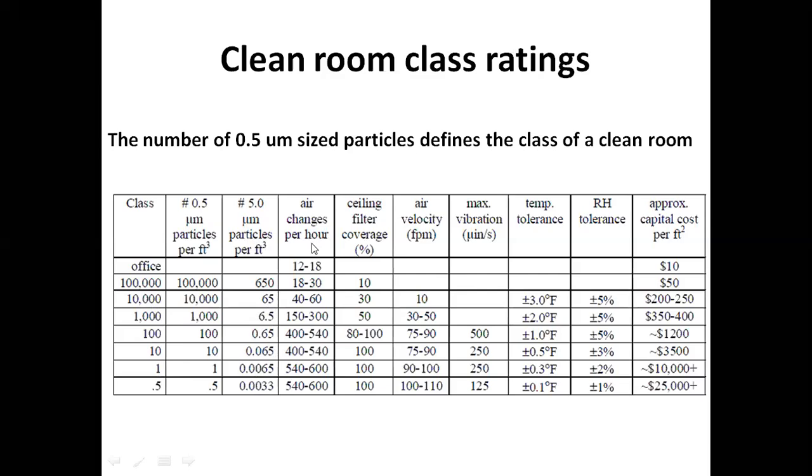Air changes per hour. How many times you have to completely change the air inside the room, meaning that you would be continuously doing the ventilation inside the clean room. Reason? Because we are using hazardous and toxic acids and bases, gases, etc. And we don't want those toxic fumes to damage or harm the people who are working inside the clean room. So normally we have to continuously change the air or ventilate the air in the clean room.